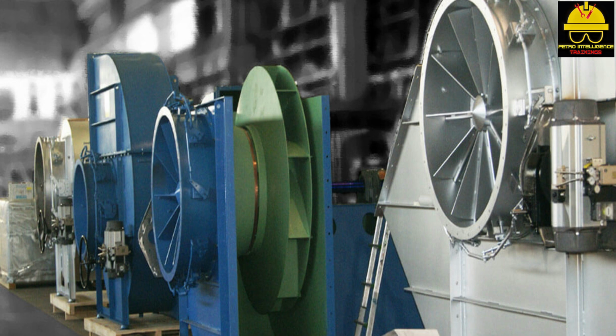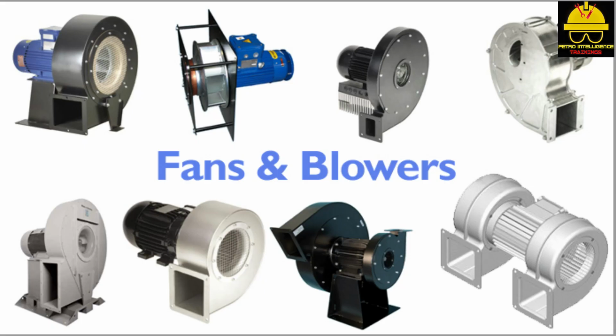Fans can be used to direct airflow into or out of industrial equipment such as cooling towers, flares, boilers, furnaces, HVAC (heating, ventilating, and air conditioning) systems, or air-cooled heat exchangers, or they can be used for ventilation of confined spaces. Fans can be classified as centrifugal, propeller, tube axial, or vane axial. Centrifugal fans are designed to move gases over a wide range of conditions. Propeller fans consist of a propeller and a motor mounted on a ring. This fan is primarily designed to operate over a wide range of volumes at low pressures and to move air from one enclosed area into another.